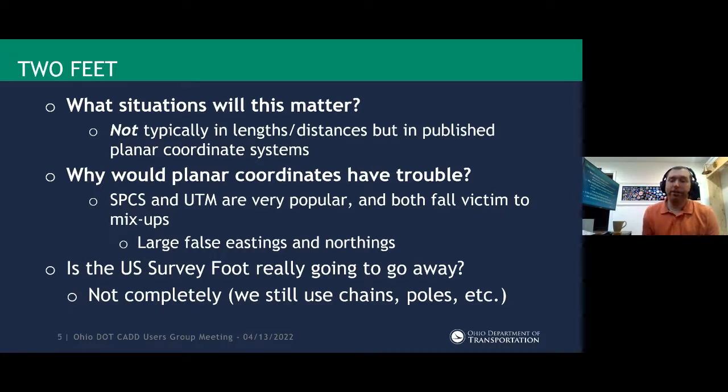Unfortunately, it's never really going to go away, because a lot of the coordinates that we have on things are still going to be valid in the future. We're going to need to know whether that's a U.S. survey foot or an international foot coordinate, because once we're into those millions, like our false eastings, we're going to see some of those 2 foot differences in a point.